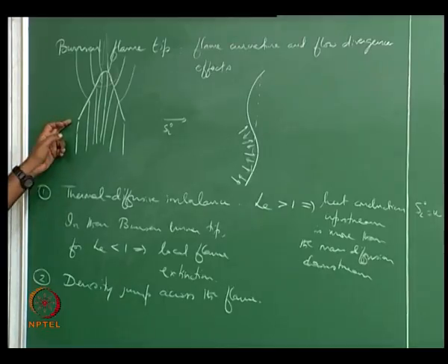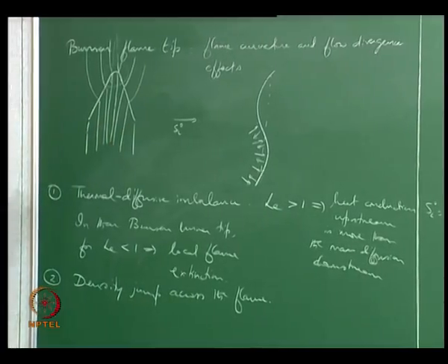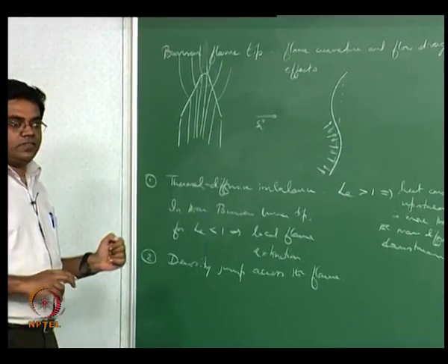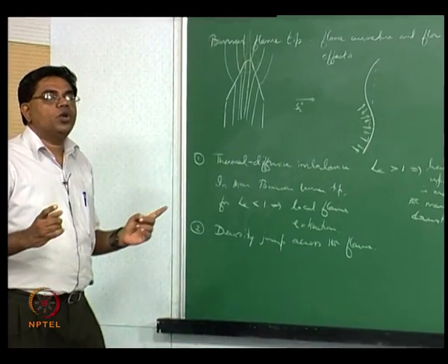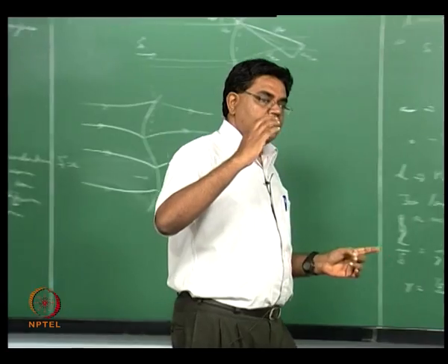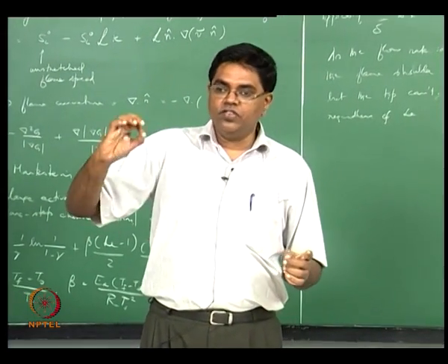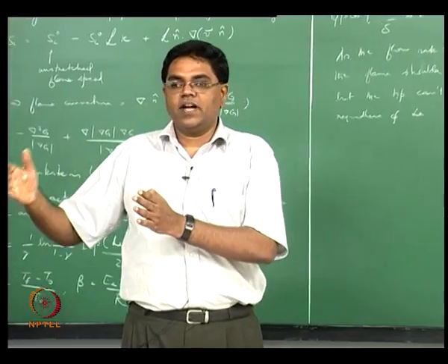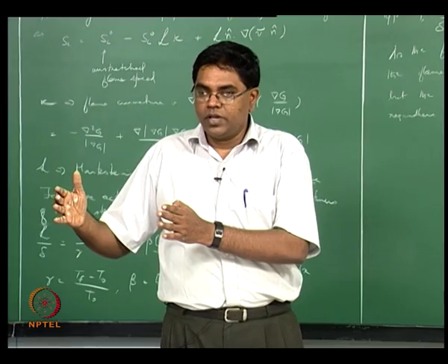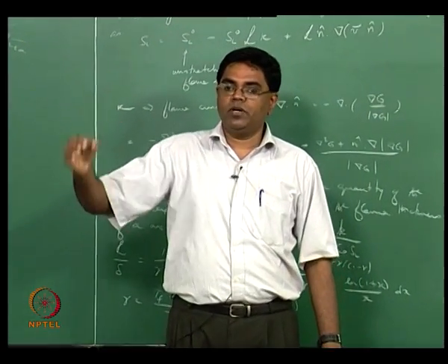But what about the base? What's going on at the base? When we did the G equation, we made an assumption that zeta should be equal to 0 at r equals capital R. That was a boundary condition we had adopted, basically saying that the flame is touching the rim of the burner.